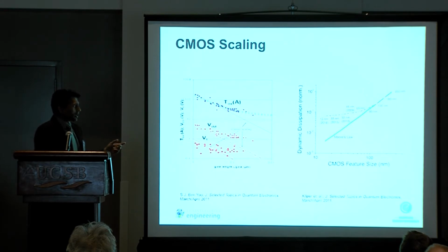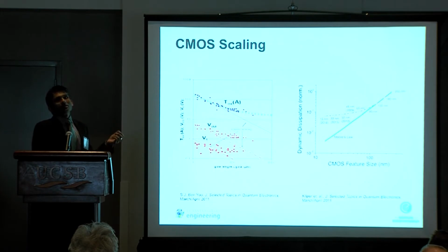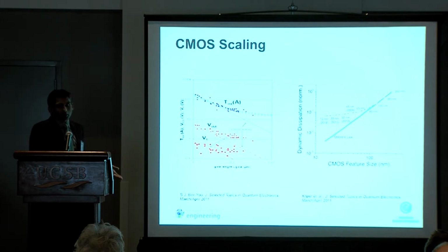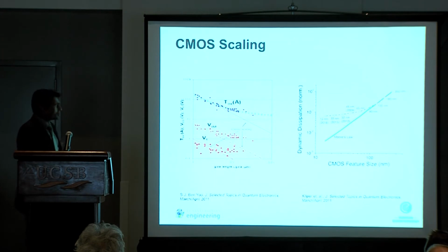Right about 90 nanometer, the oxide gets so thin that a transistor sitting in its off state and not switching actually consumes more power than a transistor that is switching, because the leakage current through transistors becomes the problem. Even if you had 1 nanoamp per gate, and 1 billion gates, you have 1 amp of leakage. So it becomes a real issue as you have more transistors and thinner oxides. There's a lot of research going on into how to make this better.